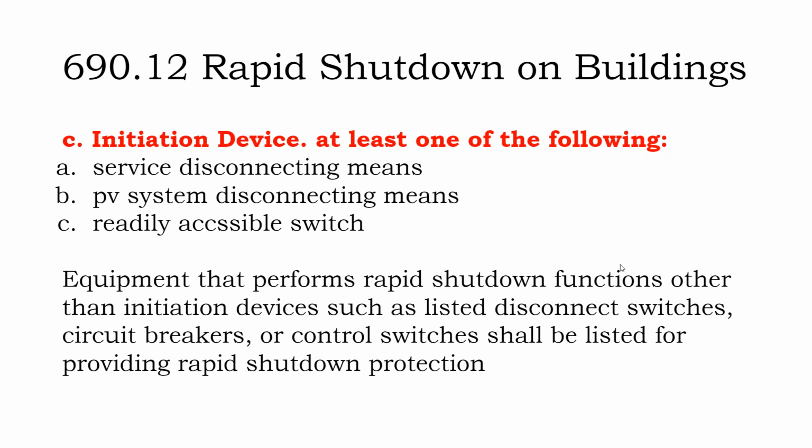But it was mainly sloppy workmanship with MC4 connectors being poorly managed, lying down in puddles and burning holes in the roof and taking advantage of shortcomings in the electronics rather than the electronics themselves.